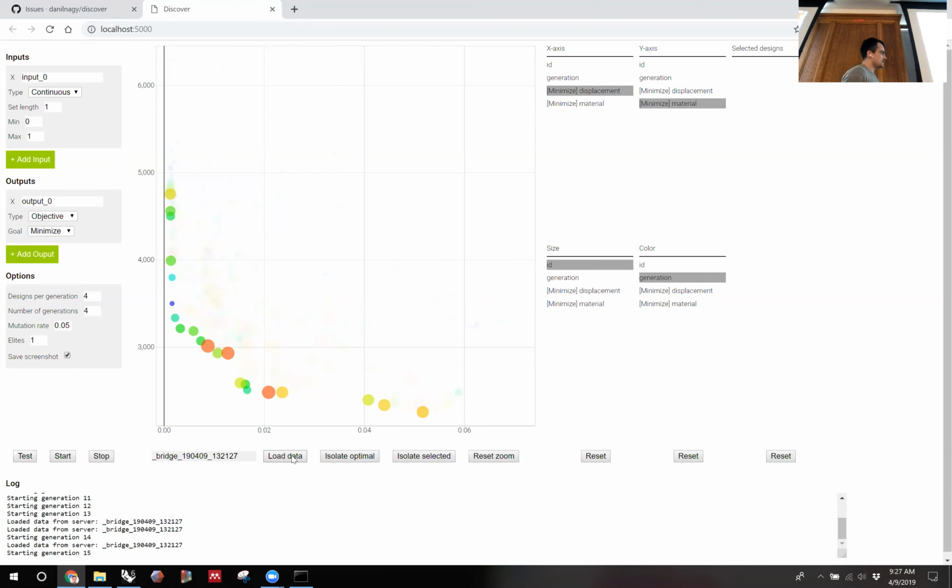So you're not actually doing better. And that might mean either you found the best designs already, so you're kind of done, or it might mean that you're converging too early. So this is the recurring pattern in this process: there's a lot of times where you're not really sure. You have to really use your intuition again and explore different variations. So if I'm not seeing more and more optimization, I might say, well, maybe my mutation rate is too high, or I need more designs per generation. Start exploring a wider range of the design space.